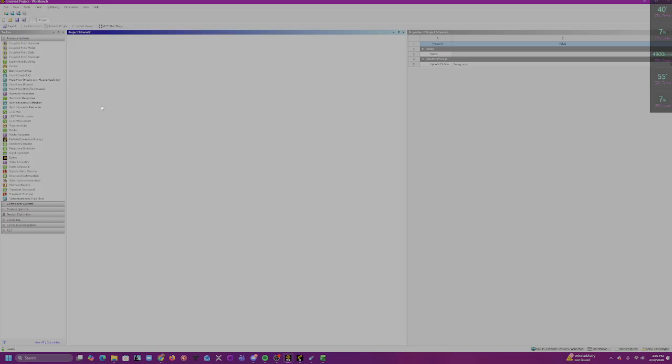Next we're going to be dragging this inside the toolbox. We're going to be getting this project out. So go ahead and click and drag Fluid Flow Fluent, and then we want to create a standalone system. So drop it in here.